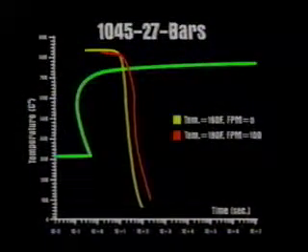This has practical significance since all quench tanks have significant fluid flow gradients surrounding the parts during the quench, which may produce significant hardness gradients. It is important to understand that quenchant flow is an important variable for every type of quenchant, including gas, water, oil, polymer, molten salt, and others.